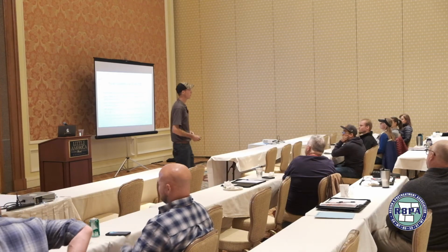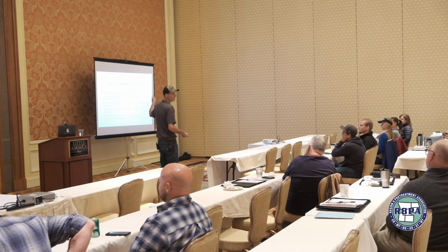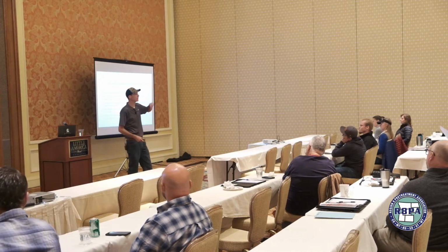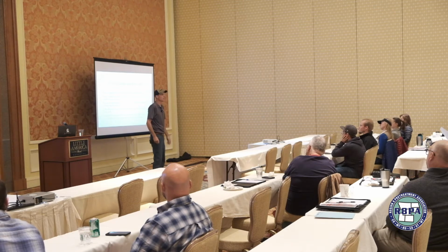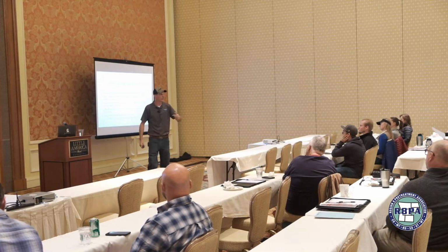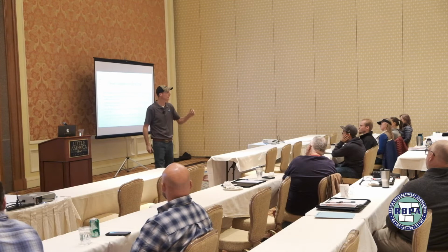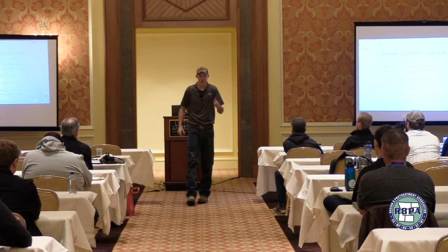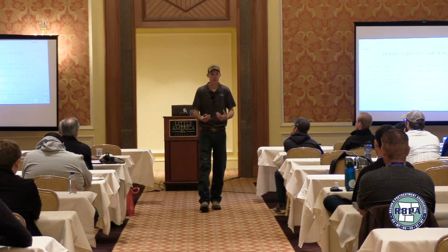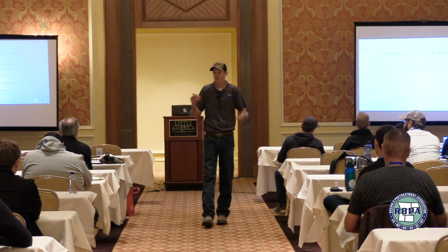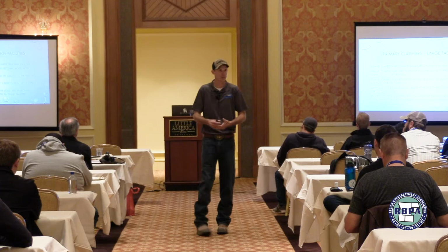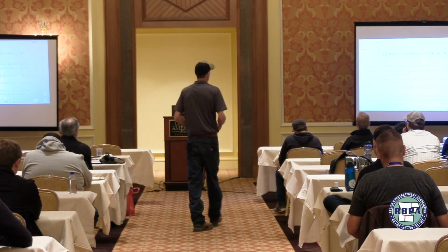So as a pre-treatment person, this is a big deal for you. Because this is your place where you can do that composite sample before that EQ and after that EQ. It came in at 2 a.m., it left the EQ tank at 2:15, but it's in there for 30 hours. You have a chance to actually collect a little bit of that. Was it toluene? Was it chromium? Was it FOG? What was it? Was it diesel fuel? You have a chance to play with it.